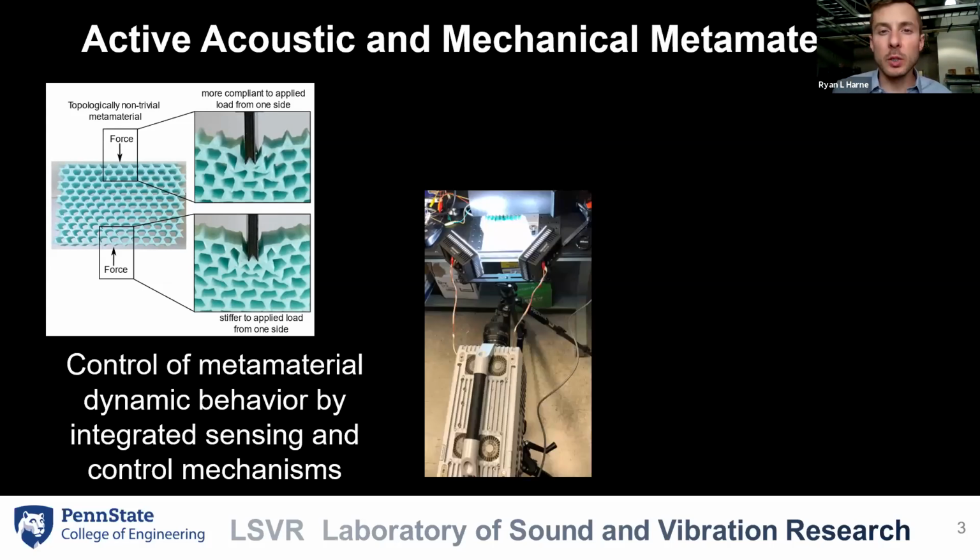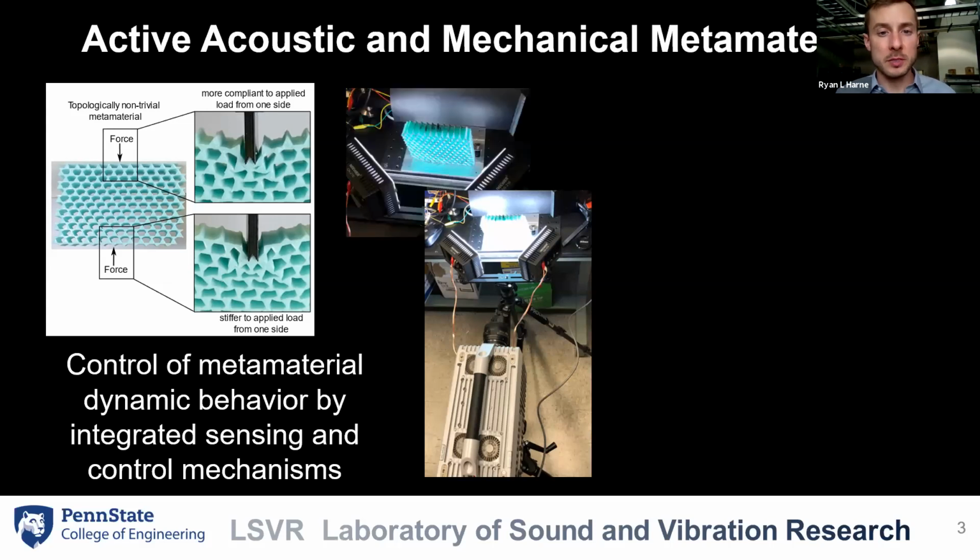We study a lot of loads applied to these materials. More recently, we're giving great attention to shock and other transient forces. This necessitates high-speed videography. So we have full high-speed recording capabilities in our lab, up to 1 million frames per second. If you're a novice photographer or a beginner photographer like me, or maybe you have a little bit more experience, you would understand that that requires a lot of light to come into the aperture. So when we perform high-speed videography, we have to saturate the object with extreme amounts of light. These are very short tests, otherwise the light heats up the object.